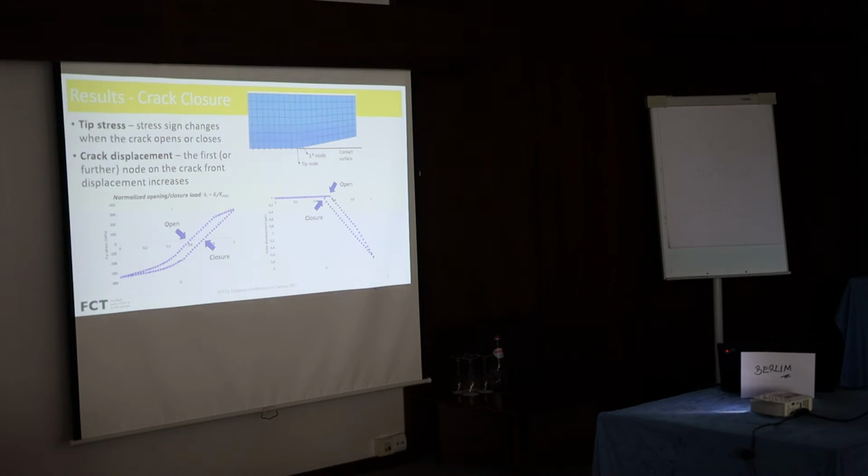For the crack closure, we use two different approaches. The tip stress, where the stress sign changes when the crack opens or closes, as you can see here, and we can observe that the crack is open in this part and closed in the other one. And we use another approach, the crack displacement, where the displacement of the first node of the crack front increases, and we obtain something like this.